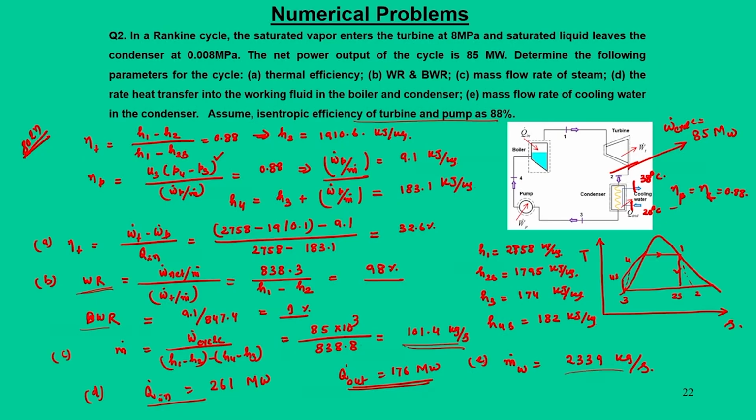Why? Because we have introduced irreversibility into the system through the component efficiency of turbine and pump. That is again the basic need of analysis or design of a steam power plant. What it says is that under no circumstances is it advisable to drop the work ratio, because it will not justify the utility of power. So, with this I conclude. Thank you for your attention.